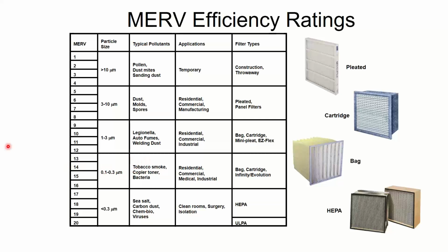Let's just say your normal air handler rooftop default filter is going to be like a MERV 6 or a MERV 8 in there. It's not that good. It doesn't catch that much stuff. The main purpose of a regular filter is to keep debris off of the evaporator coil so my evaporator coil can still do a decent job of heat transfer. Because if the coil gets dirty, then obviously I have to cool down the refrigerant, to cool down the coil, to cool down the fins, to cool down the debris, and then cool down the air. I got another layer in there. So it's mainly to keep my coil clean so I don't lose cooling capacity and cooling efficiency. It has nothing to do with your health and well-being. If you want health and well-being, you need to get down over here.